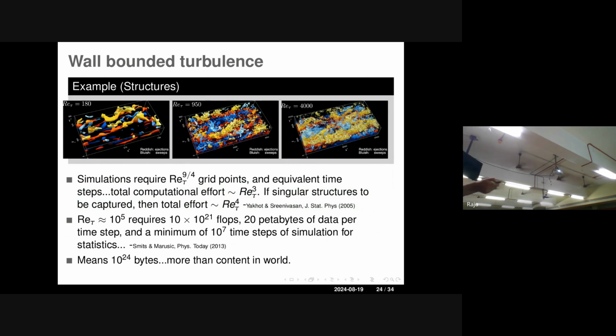In some sense, this can be understood through low-dimensional models like high-speed and low-speed streaks. That kind of low-dimensional way of separating gives you certain information. But these tiniest structures have huge velocity gradients. The size is small, but the velocity gradients are so large, so the turbulence stresses will be so high at that location. So now the integral of the volume of the stresses: is that very large compared to these large-scale or small-scale structures? It is not singular in a mathematical sense.